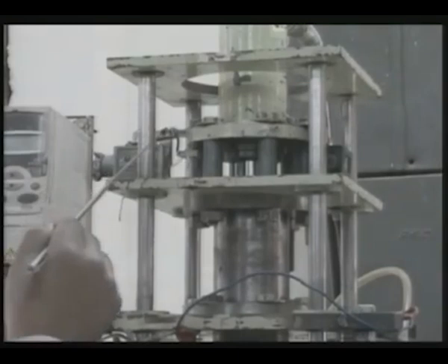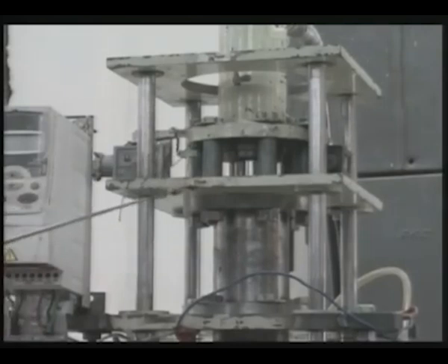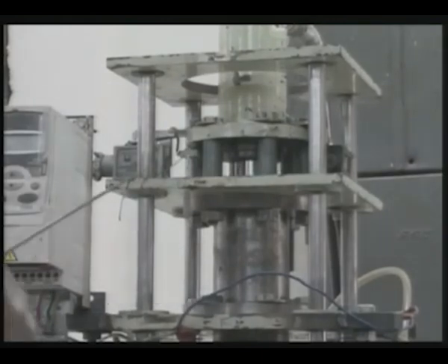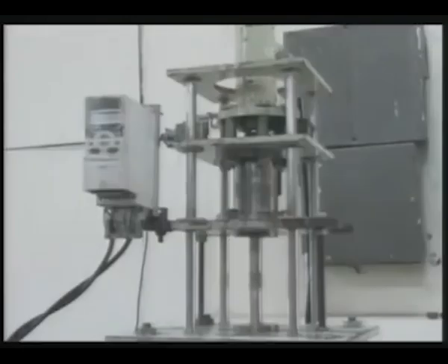And this is the limit switch which is attached to the piston of the medium cylinder, and it changes the current to the hydraulic unit, and the flow of fluid is reversed. The purpose of this limit switch is that it controls the stroke length of the piston in the medium cylinder.